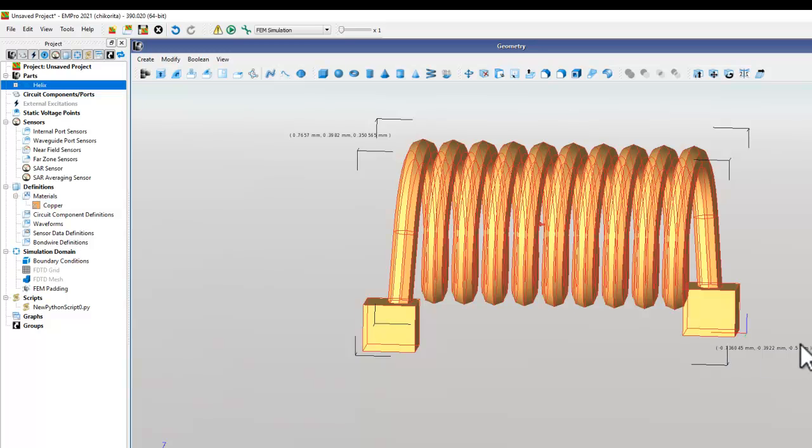Otherwise, when you place this component in ADS, you need to remember this offset so that you can cancel out this offset from the 0, 0, 0 location. So I don't want to do that because I know this object has to be used in ADS. Why would I like to remember it? So I just want to shift this origin back to 0 in Z direction.